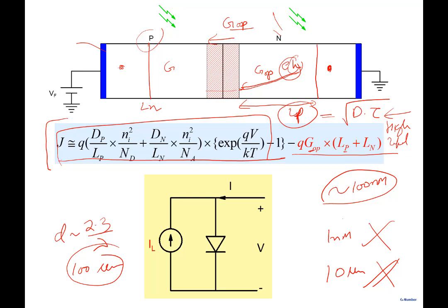So that's the reason why solar cells are all made on very, very high quality silicon. And that makes the solar cell also very expensive, because if it's high quality silicon with very few defects and all that, it becomes an expensive thing. The other thing that you may be wondering here: why can't the hole just go here? Sorry, the electron hole pair that is there here, it can also go here. There is no field at this particular point, right? It's a neutral region. The hole can diffuse here also, and it can recombine also. You want the hole to go here.